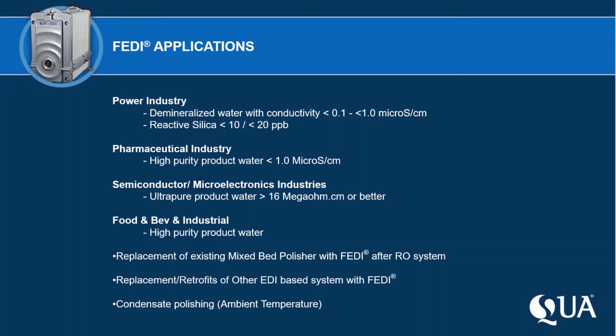They take water, they turn water into steam, and they use the steam to power turbines, and then they condense it down. And they almost have a closed loop system, right? They recirculate their condensate back, they turn it into steam, and they have this closed loop type of system. One of the things they can't afford to do is have silica precipitate out in the turbines, because it reduces the life of the turbines and the components of the power industry. So the power industry is concerned about silica.